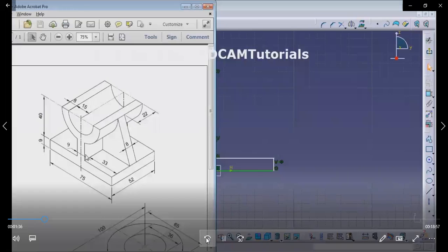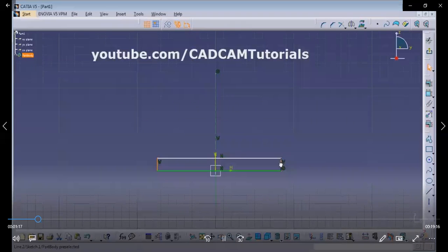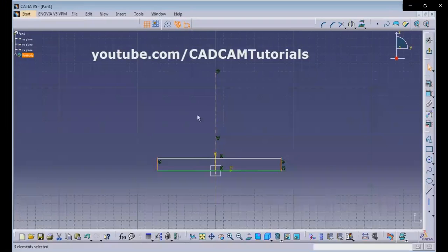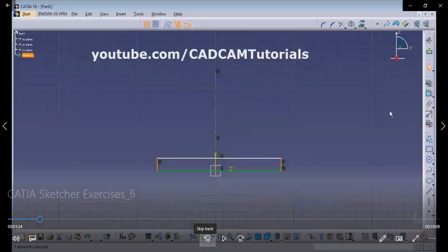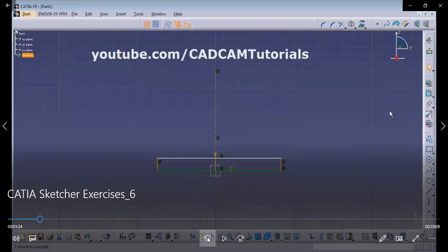Then next is the selection of the axis for the symmetry option, which should be considered last. Select the other entities first, the symmetry entities, and then this axis at the end.